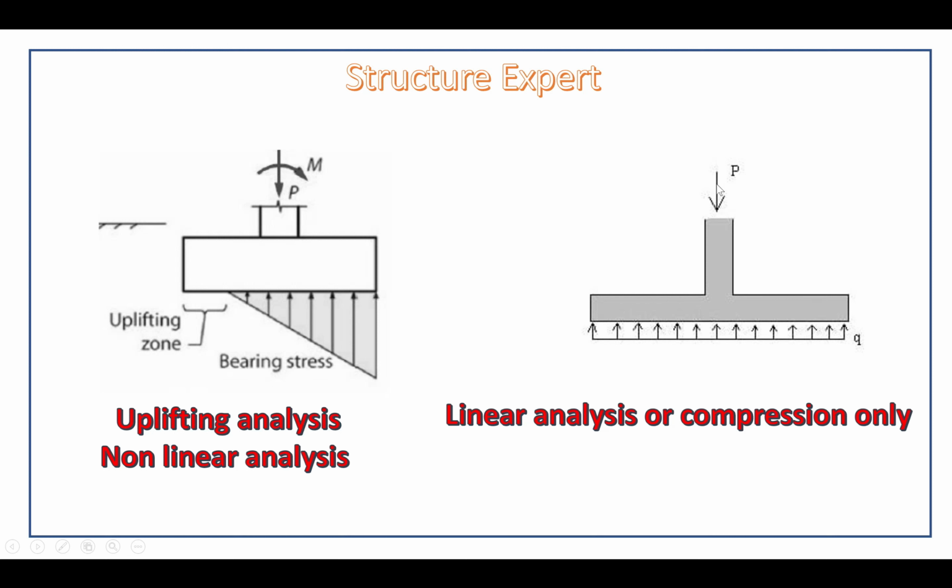When you apply only axial force, the bearing stress will be fully distributed in the base of the footing. In this case it is rectangular, or linear. You see the contact stress, and this one we have eccentricity.